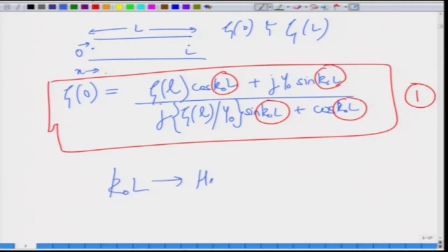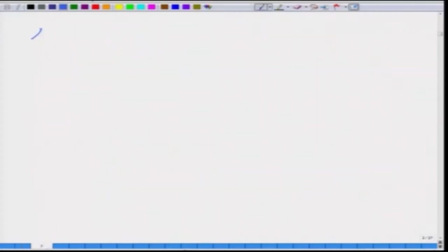Let me put this again here, Helmholtz number. So, when k naught L is much less than 1, then obviously we can make a lot of simplifications, and then your lumped system analysis will apply. We can have different scenarios, of course, like we discussed, either the frequency is very small or the length L is also quite small. In either case we will see how we go about it.